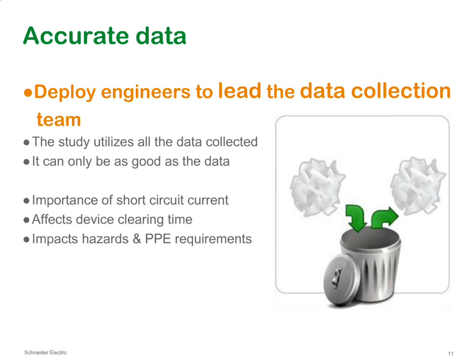Suffices to say that the right way of doing this is to make sure, preferably, that the professional engineer who is going to be ultimately responsible for signing and stamping the work is on the site and leads the activity, leads the people. Or second best is to have another professional engineer, or somebody who is qualified for arc flash analysis, on the site leading the activity. That way you make sure that any assumptions made, any judgments used, are appropriate judgments and are going to provide the right data for you.